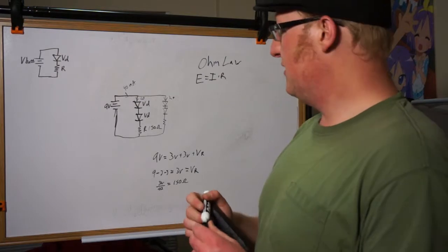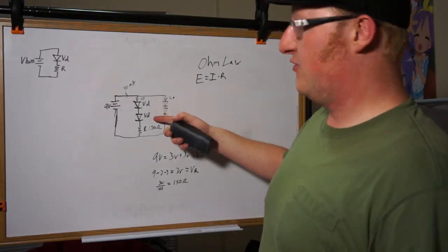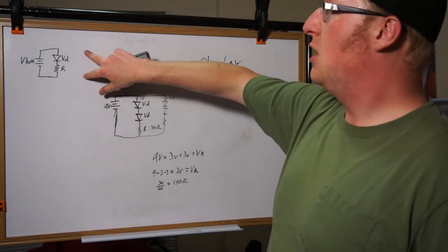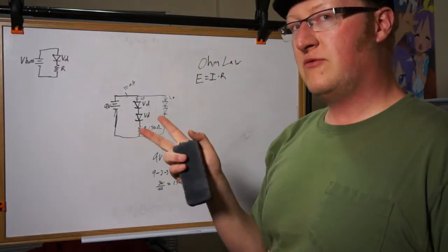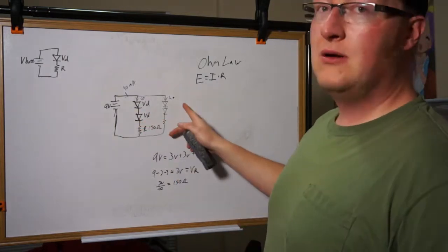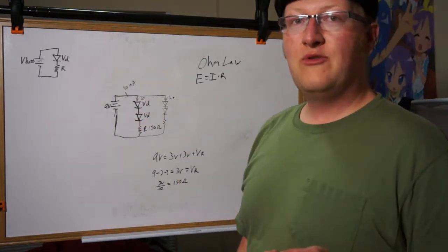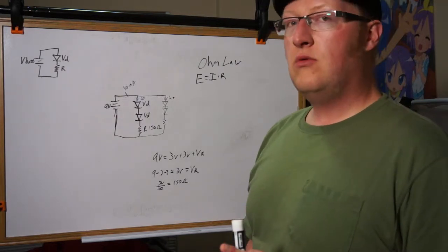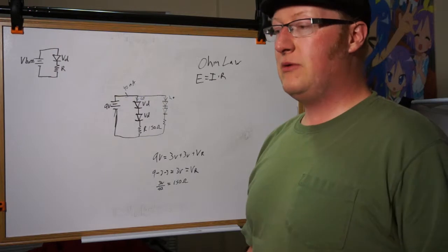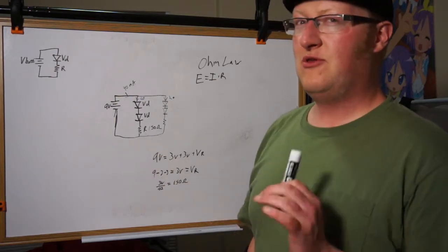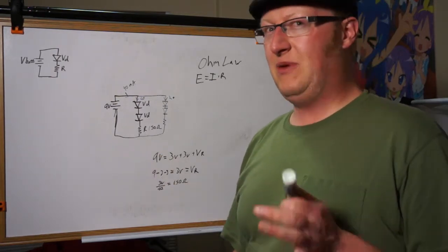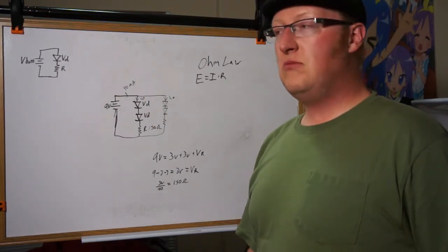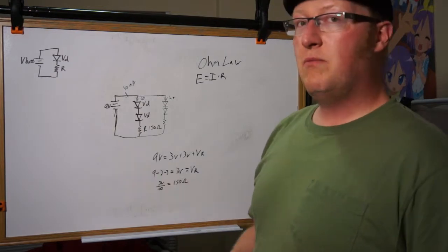So, obviously, we want to put as many of these LEDs as we can together. Because before, let's say we made 2 of these, so 20 milliamperes each, we would only have 2 LEDs lit up for our 40 milliamperes. Here we've got 4. Now, there are other ways we can go beyond this that will allow us to get a lot more out of it without having to spend more, basically without even having to have the resistor at all. But there's a whole bunch of exceptions and exclusions, and you have to be careful with it. We're going to cover that in the next video, so if you're curious, feel free to tune in. If not, this is probably the best implementation.